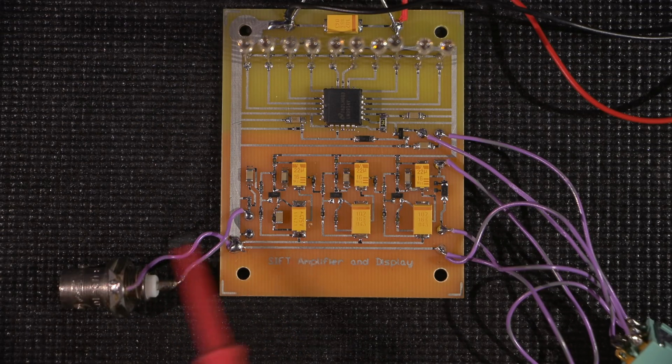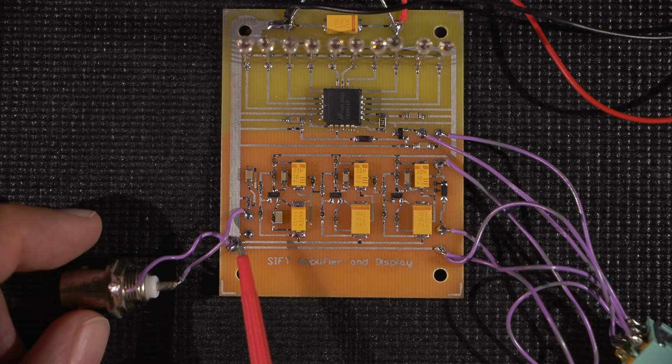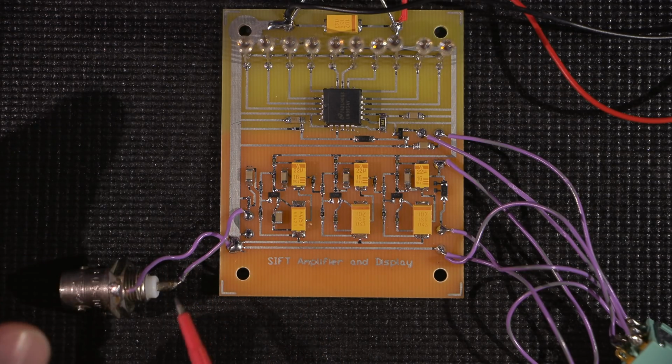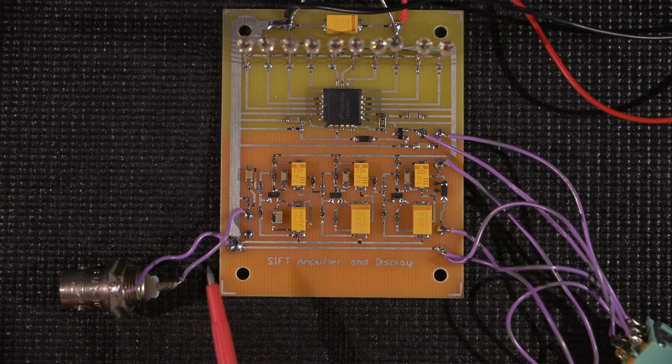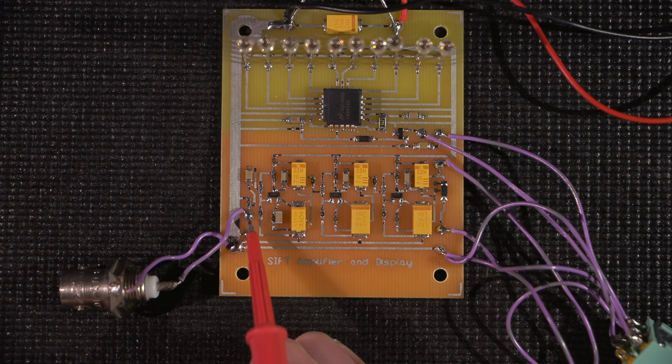All right, for this particular application, I'm going to be using my probe on ×1 in the beginning here, just because this is such a low level signal. So having a ×1 and a ×10 probe is very beneficial for troubleshooting. So again, AC coupled, ×1, and what I'm going to be doing is probing this point here.